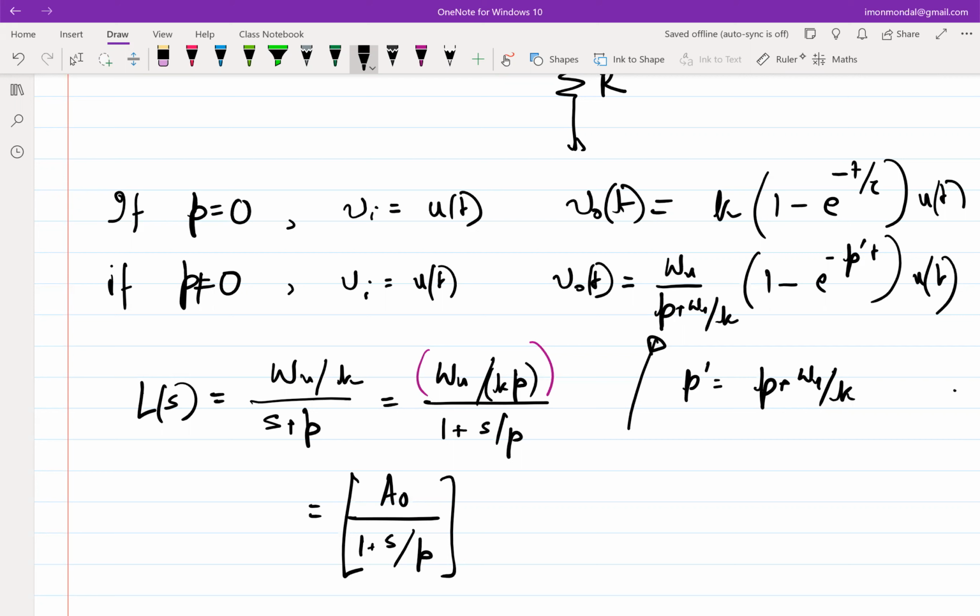Right. So I would encourage you to do it yourself and validate that this is indeed mathematically true. But from the arguments that we laid out, it seems that it should work, because the UGB of the loop hasn't changed. Mathematically, you will see there is an extra term, but that extra term will be negligible with respect to omega over k. So we can neglect that extra term, which essentially means that my UGB of the loop hasn't been impacted, at least by the Bode approximation. If the UGB of the open loop system hasn't been impacted, then the 3 dB bandwidth of the closed loop system should also not be impacted.